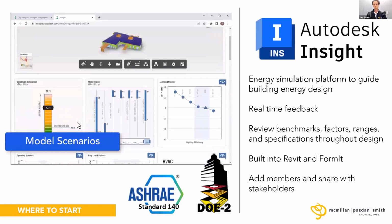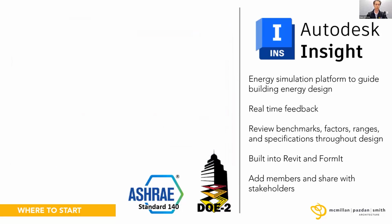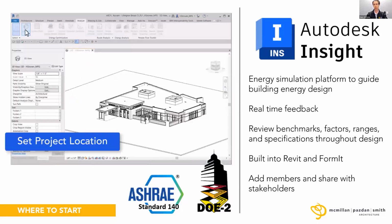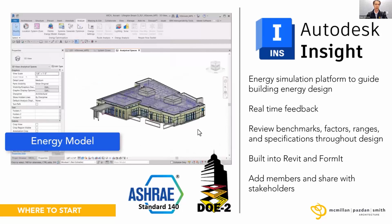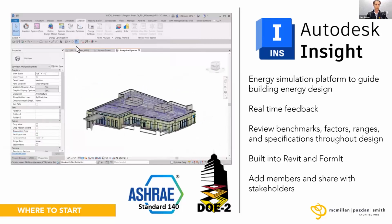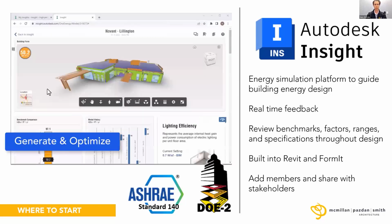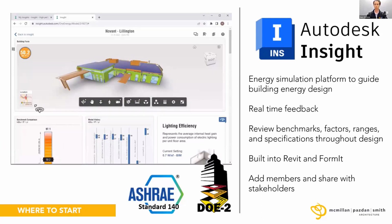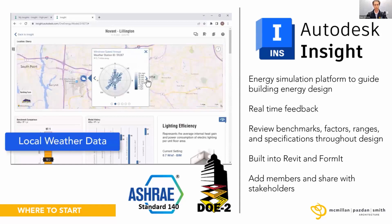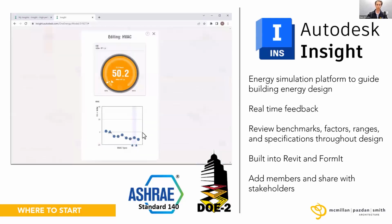Insight is an energy simulation platform to guide and show different scenarios that you can do within your building. You get real-time feedback, you're able to plug in the location, set different standards, dial in your energy factors, and review the benchmarks via ASHRAE 90.1 and the Architecture 2030 benchmarks. That gives you predictive outcomes for how your building is going to behave. Then you can add in your members and share with your stakeholders for informed decisions throughout the design process.